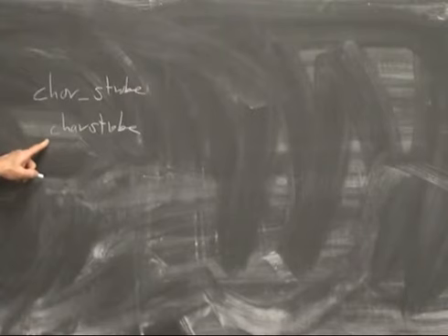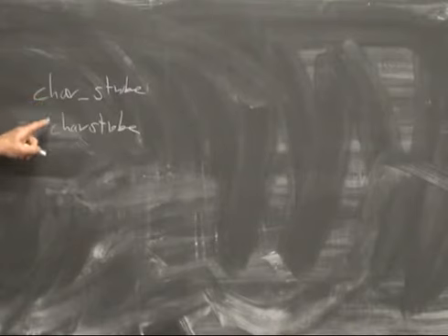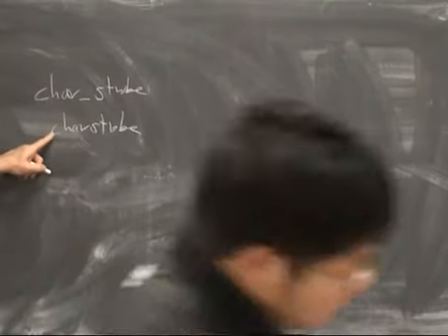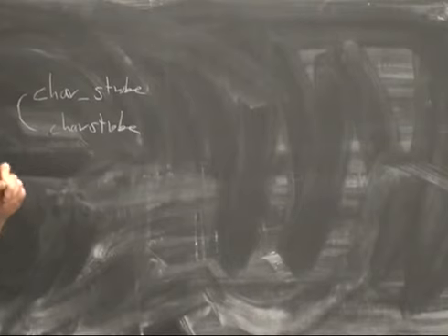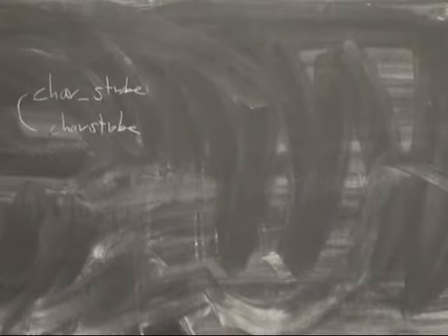And Quartus just happily synthesizes, makes up a variable with a name that is never defined, and assigns it the value of 0. And it never changes. You won't ever find that because it doesn't throw an error unless you check the warnings, in which case it will say created implicit net. If you see any warning that says created implicit net, you're doomed unless you fix it.